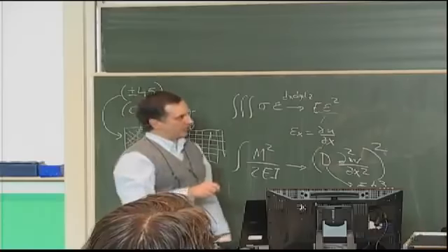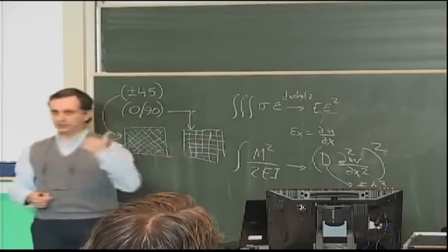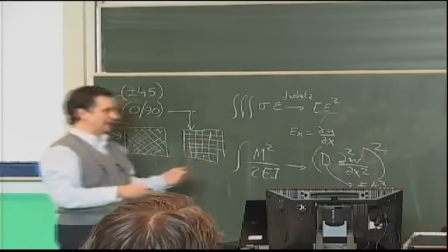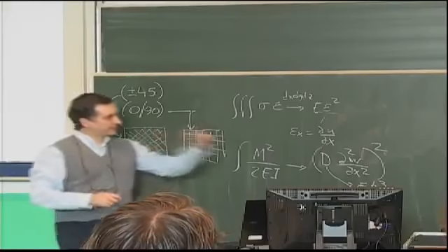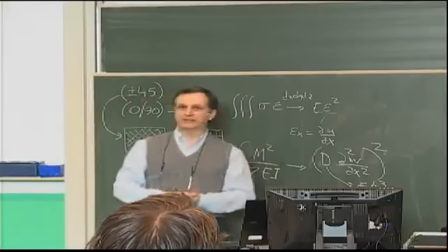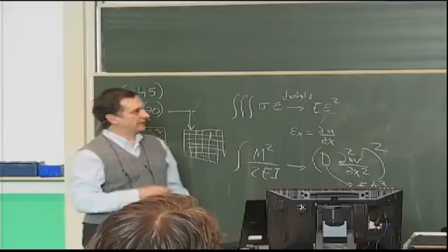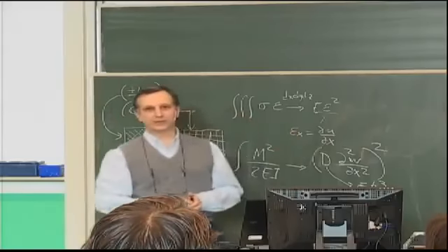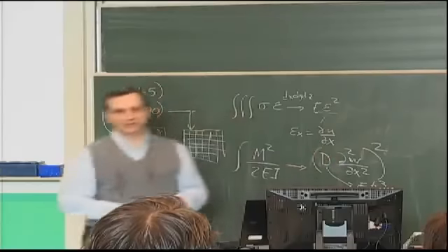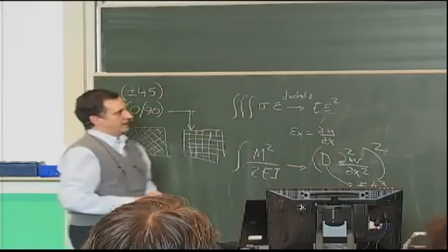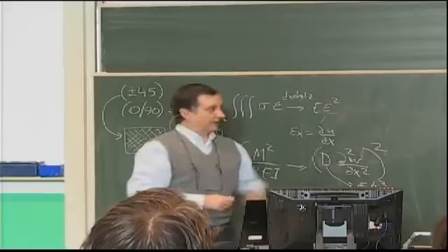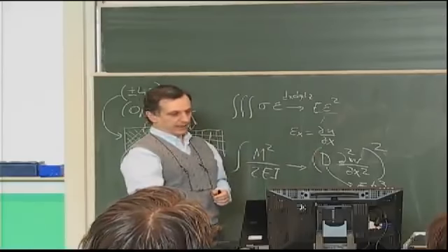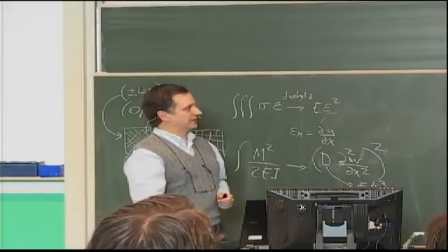So while the top line only involves the in-plane displacements U and V, and the bottom line involves the W displacement, in the middle we have them combined. And you can see how that really complicates things and why it's very advantageous from a mathematical, algebraic perspective to have a B matrix equal to 0. That's the general expression in terms of displacements.